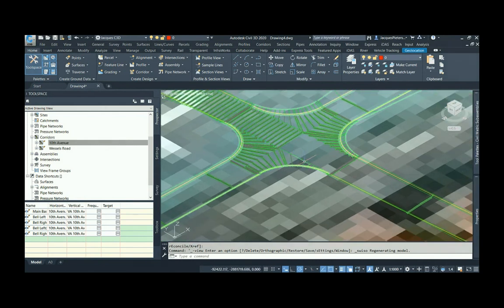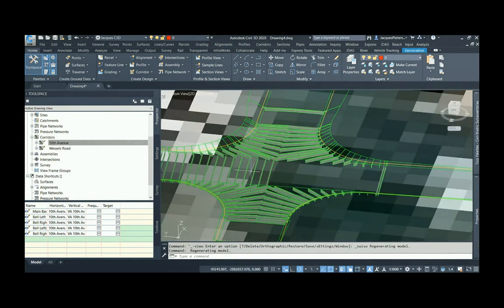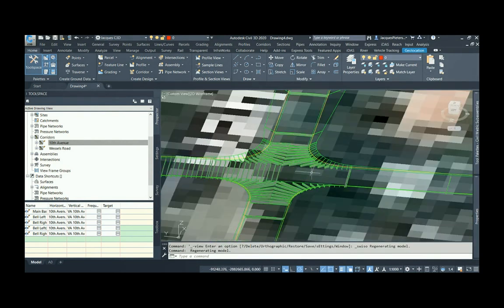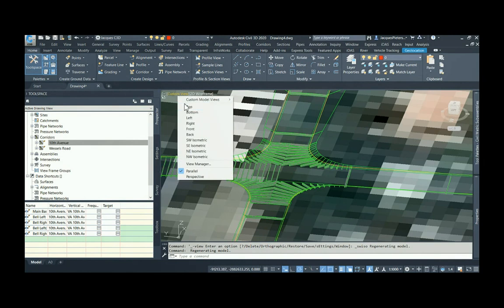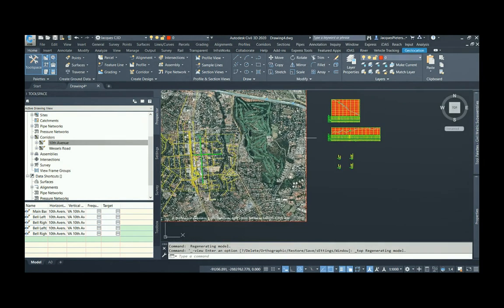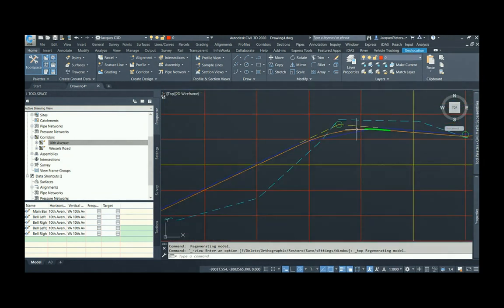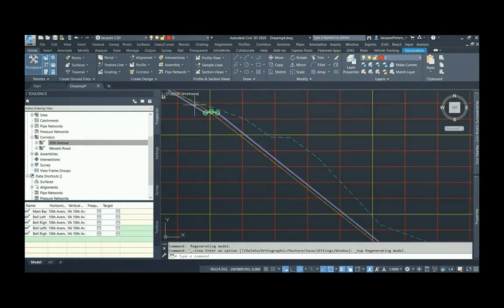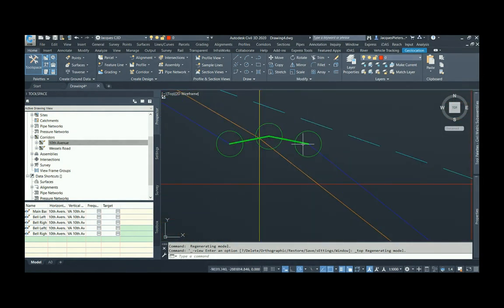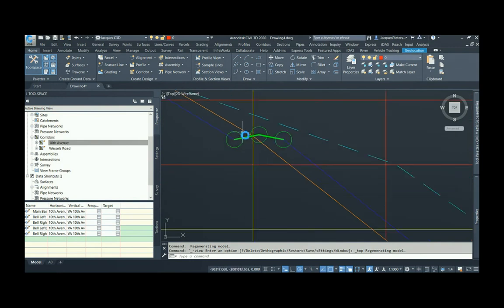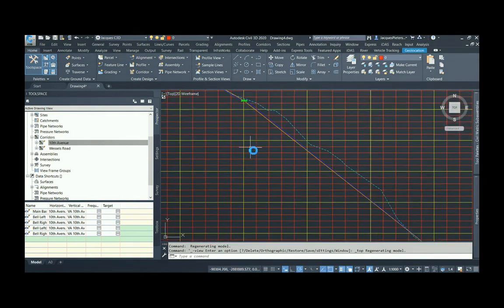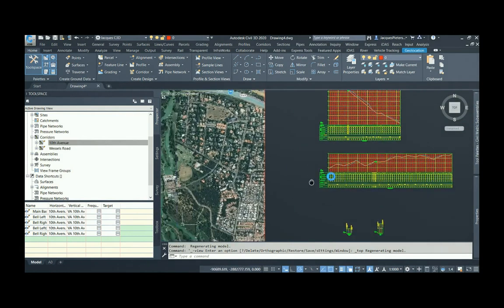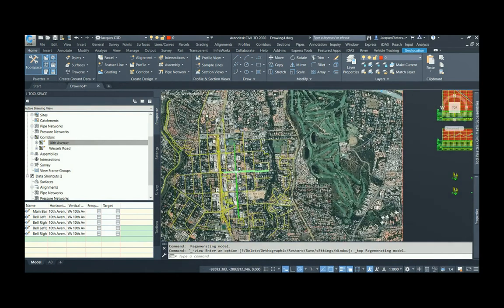It saves you so much time and hassle just using Devitech IDAS in Civil 3D. As you can see, it generated very nicely. And if I go back to my top view, you can see even in the profile views, it brings it up. And it's so awesome, it actually ties in those two points on the ETWs. I didn't have to do this. You can still add curvature to make it more smooth if you want to, and just rebuild the corridors and it will look much better. And it's ready for plan production.